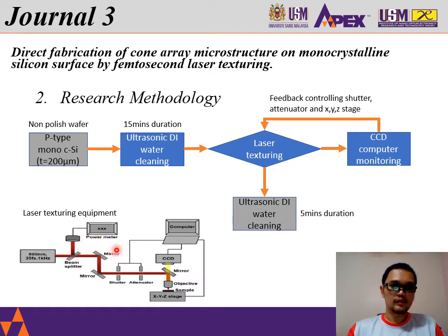One beam goes to the power meter to control the laser power, and the other goes directly to a mirror, which guides the laser beam into a shutter as well as an attenuator, and is reflected by another mirror onto the sample surface, which sits on top of the XYZ table or stage.